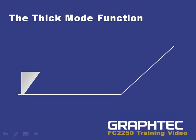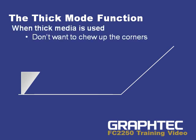If you're cutting thick materials, the thick mode is a function that you're going to use quite extensively. What happens when the cutting blade is coming up to a corner in a thick media? It tries to navigate around the corner. If it doesn't do anything else, what often happens is it'll chew up the corner. So that's what the thick mode function is all about.